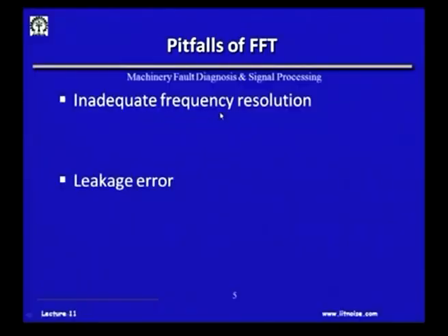So, in the FFT process, if I have taken care of inadequate frequency resolution by increasing the number of lines of FFT or increasing the block size, I would be able to capture any unknown signal which I would otherwise have missed. Another is to have a right estimation of either the frequency or the amplitude of the signal, a windowing function has to be used.